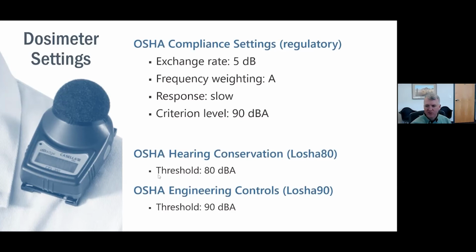And something that I found interesting, when I was looking into the history of the standard from OSHA, in 1972, NIOSH published recommendations for an OSHA occupational noise standard to update it, which included an 8-hour TWA exposure of 85 dBA, but they said keep the 5 dBA exchange rate. So they did. In 1973, they maintained the original 90 dBA PEL with the 5 dBA exchange rate. But what I wanted to mention is why the 5 decibel exchange rate, because mathematically it does not work. It does not work with logarithms without a little work. So even with noise energy exposures, it doubles every 3 dB.